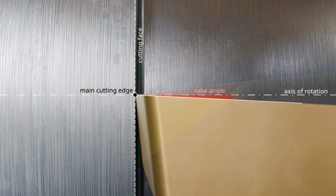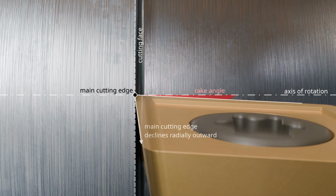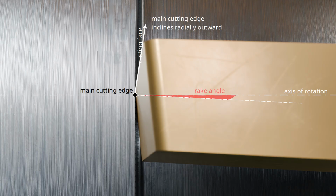The rake angle, from the given perspective, describes the inclination of the rake face in the axial direction of the turned part. In addition, the rake face can be inclined not only in the axial direction but also in the radial direction. In the present case, the indexable insert is not inclined in the radial direction. However, it can, for example, be inclined downward in the radial direction as shown. An inclination upward in the radial direction is also possible.